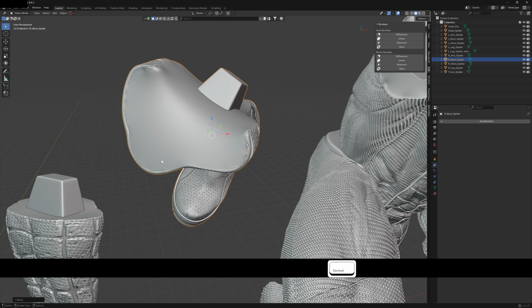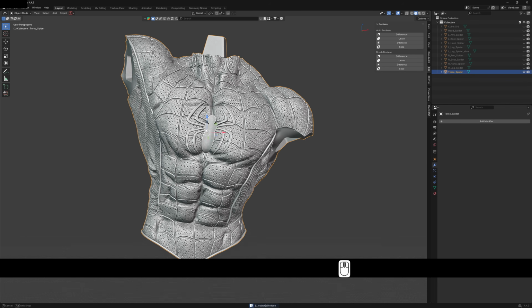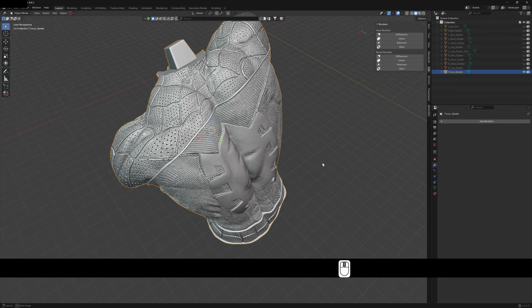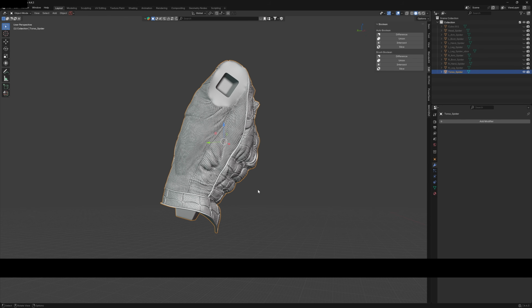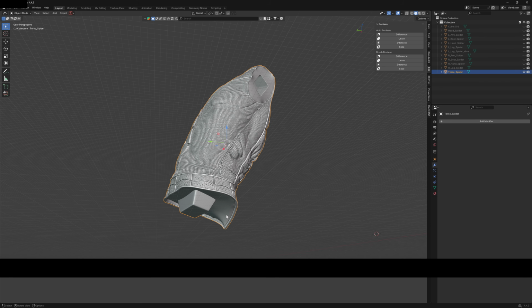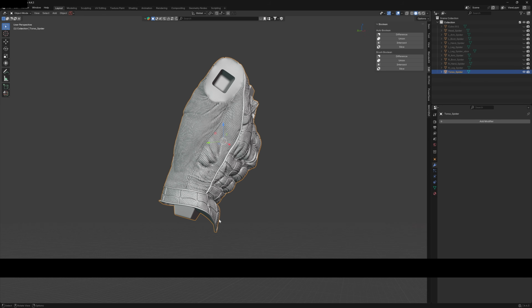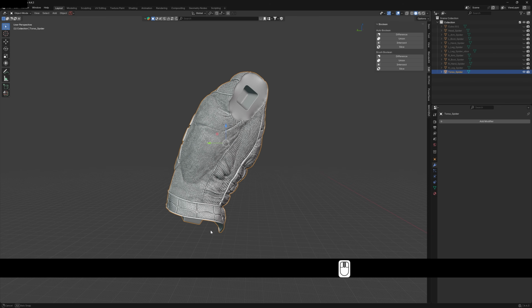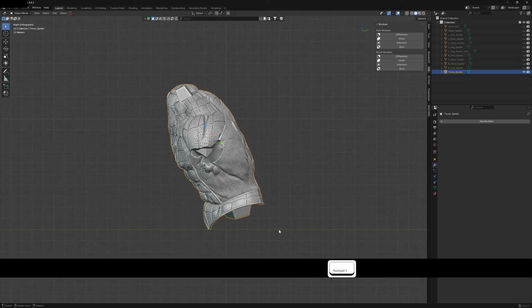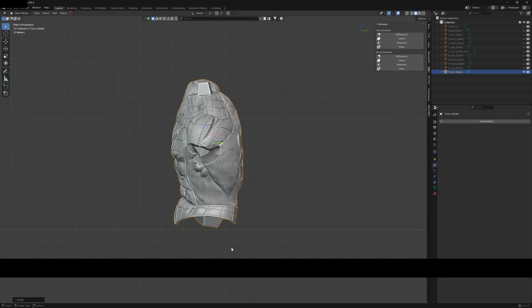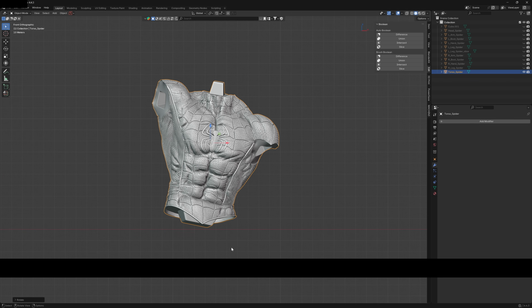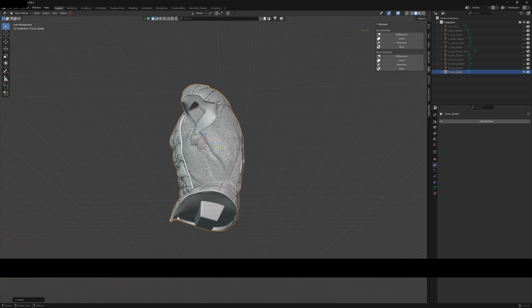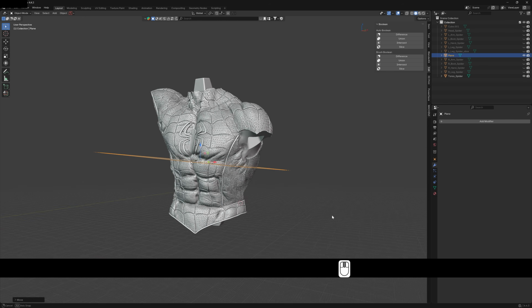Let's have a look at one more. I'm going to look at this and think, what can we do to get a really good result out of here? Okay, it's this thing that's worrying me here. This sort of droopy thing printing, that's not going to print on FDM very well if you just print it like that. I mean, you could, if you press 3, rotate on the X, 1, rotate on the Y. You could try printing something like this, but I can just see this getting to be a complete mess.